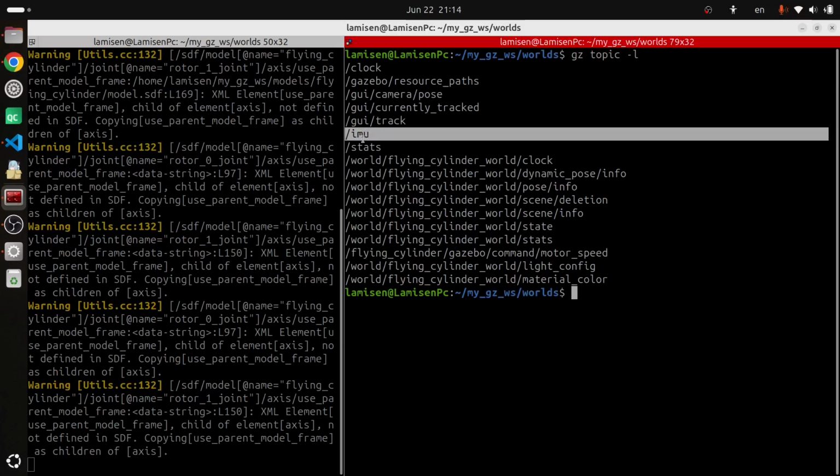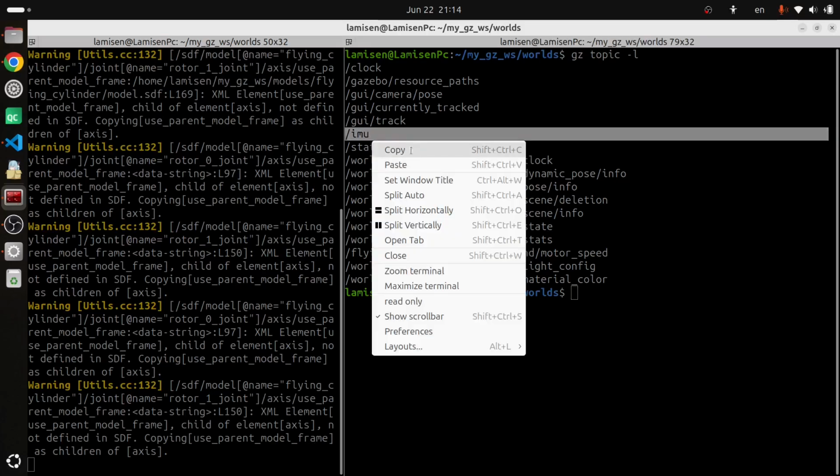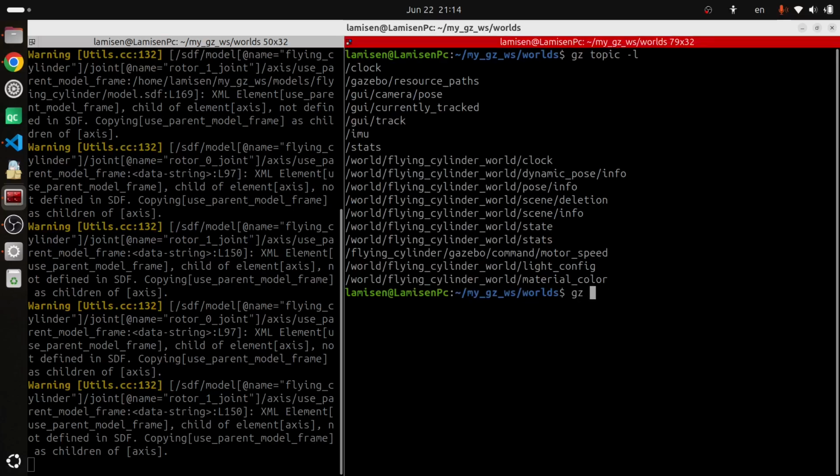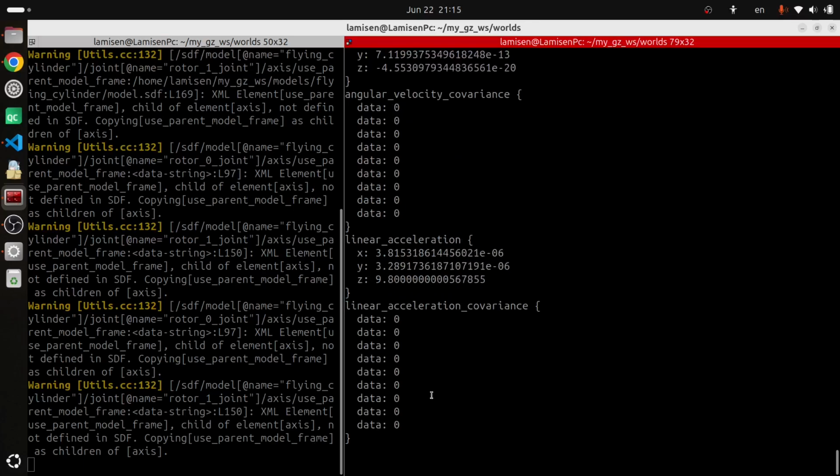If you want to see the content of this topic, we should use gz topic -e, I think, for echo, and -t to specify the name of the topic, and paste your topic name here. Okay, as you can see, we are receiving the real-time IMU data. I'm stopping it here just to see what's happening.